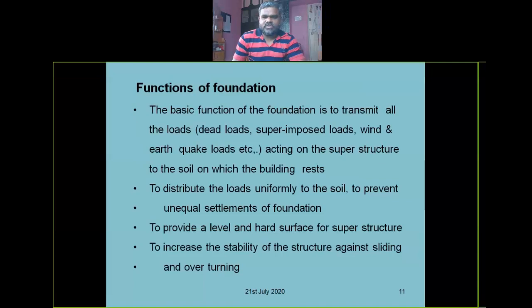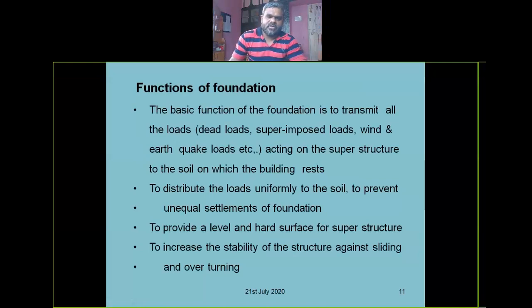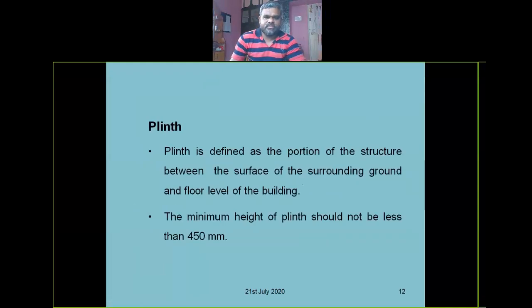To distribute all loads uniformly to the soil, to prevent unequal settlement of the foundation or of the building, to provide a level and hard surface for the superstructure, and to increase the stability of the structure against sliding or overturning, right? So our structure should be strong enough to resist sliding or overturning due to wind or any earthquake effect, right? So next is plinth.